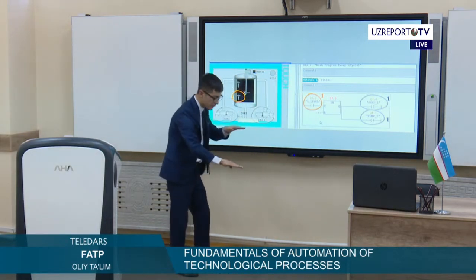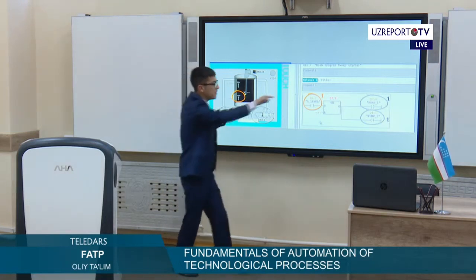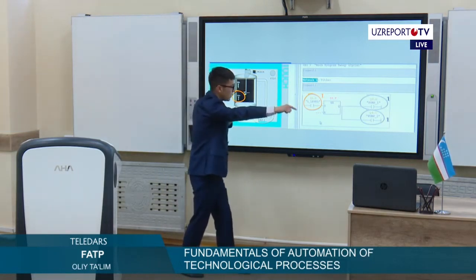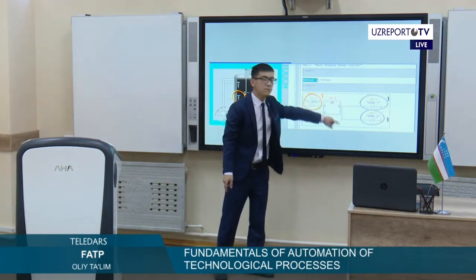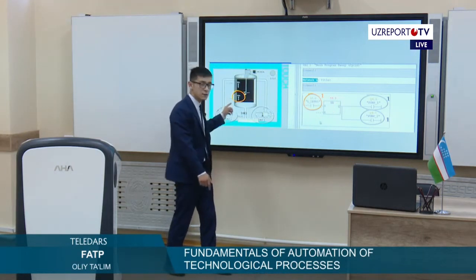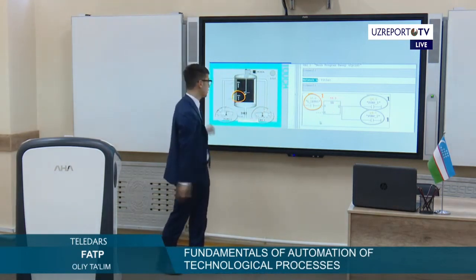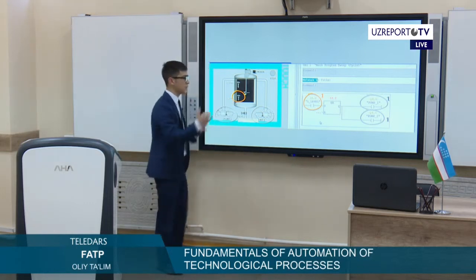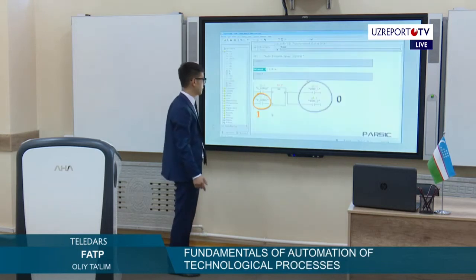It means when the sensor has a signal, it gives it to the controller, and the controller chooses to switch off pump 1 and pump 2. When the signal is gone in the sensor, it means the signal is out and the controller makes a decision to switch on the pumps. Switch off and switch on according to the level sensor.